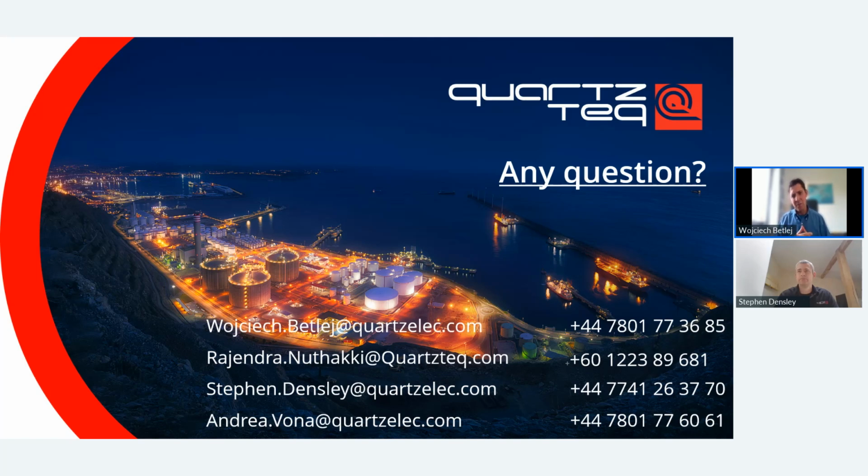Having said that, because as a company we've tested hundreds, thousands of machines, we have a large database with different machines and with different PD values. So we roughly can say what is a good PD value and what is a bad or wrong PD value. But again, this depends on the type of the machine in operation. But please let me emphasize, PD is the unique feature of every generator, and the only good way to do it is to look at every machine individually.